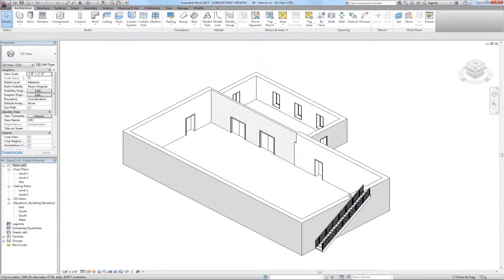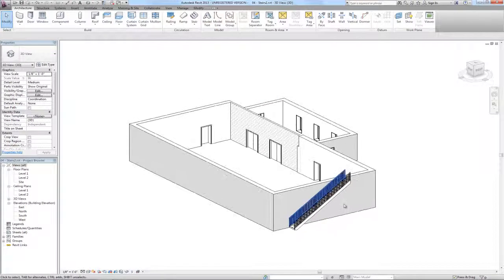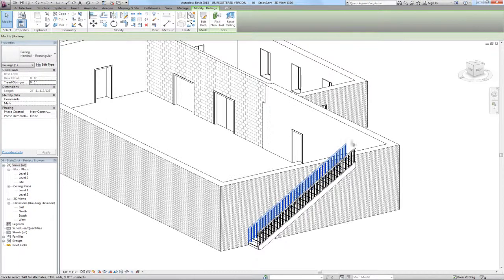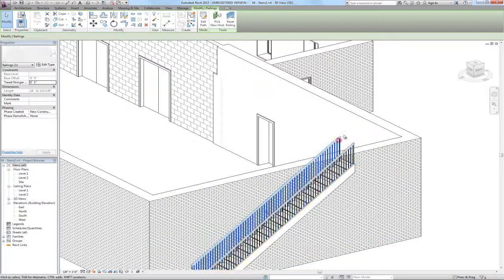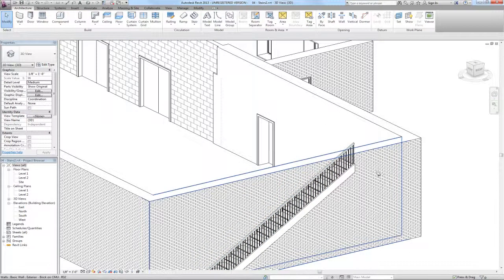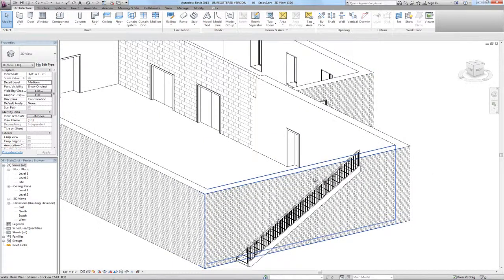If we go to our 3D view, we can see the stair went from level 1 to level 2. And if you remember, the exterior walls right now are set to go up to level 2. So it makes sense that the top of the stair and the top of the wall align right now. We'll notice that when we created the stair, two railings were automatically added to each stair. These are separate elements that are hosted by the stair, so we can select one and delete it at any time if we want. Another railing could be added later. So that's the simplest way of creating a stair.